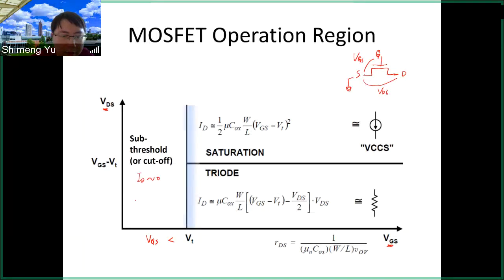And to be accurate, we discussed this is proportional to the exponential of q(Vg minus Vt) over mkT. So this is an exponentially small number because Vg minus Vt is negative. It's an exponential decay function into a very small value. It's very small, but it's non-zero. And we discussed why we want to consider this one, because this will contribute to your leakage power. Even when your processor is in the sleep mode, you are consuming power because of this one.